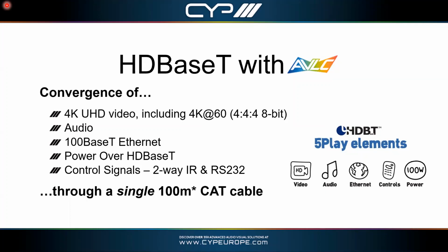So the adaptive section of it is really important, because if you don't have that adaptive section, what basically happens is it doesn't matter what you put in, whether it's within bandwidth or not within bandwidth, it will be compressed anyway. Whereas with the adaptive visually lossless compression, the compression will only actually start, because we have chips in there that are measuring the bandwidth. It will only actually be told to engage when the bandwidth goes beyond the 10.2. So when you're using 1080p, even deep color 1080p, you won't get any of the compression kick off, but as soon as you need it, it will automatically start.